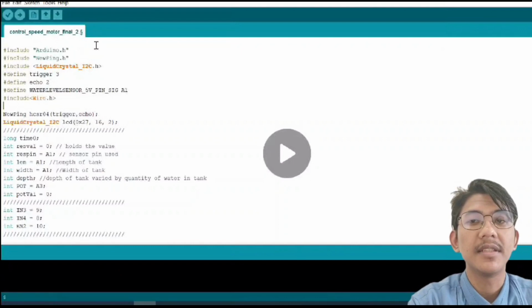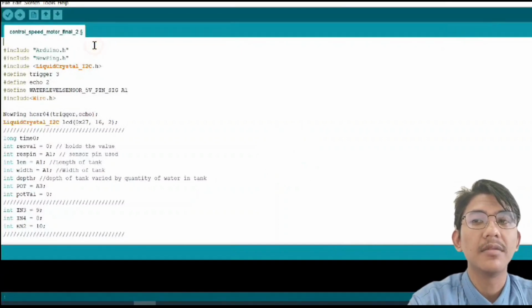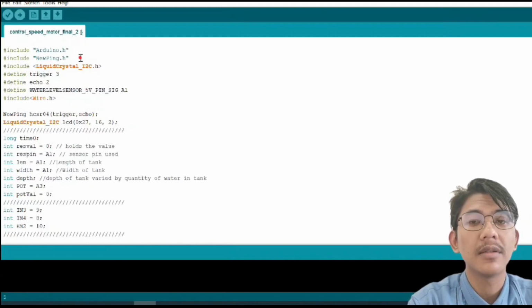My name is Idris. I will present about the smart shower coding. First of all, the code includes Arduino.h for Arduino, NewPing for the ultrasonic sensor, LiquidCrystal_I2C for the LCD, and includes Wire.h as an additional library.